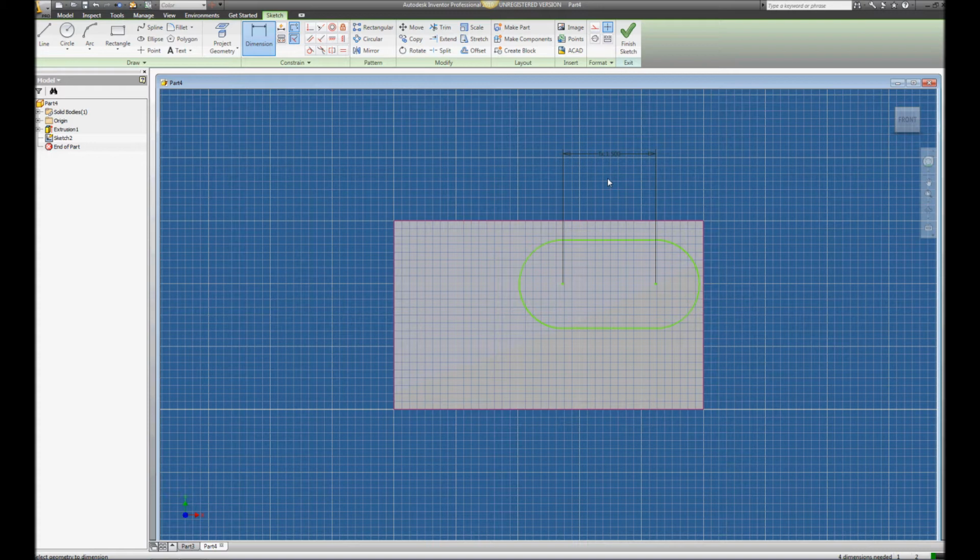Next one, we're on D5. Slot width location. 4/5 of the overall plate width. Now looking at page 3, it kind of tells us where we need this dimension to be. So D5 is going to be from this circle's center point and this circle's center point only. Do not use this one. This one right here. So we need to grab our dimensioning tool and we need to dimension the width.